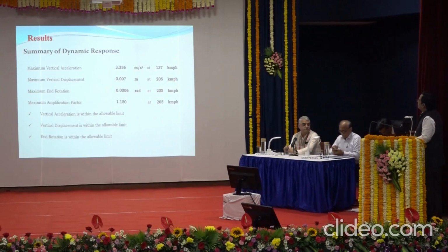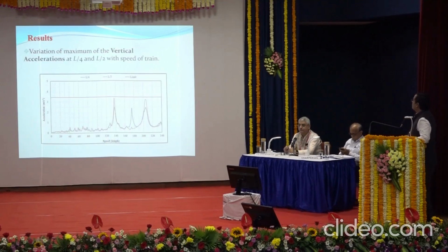So this is the summary. The result was like this. Maximum vertical acceleration was 3.336. Maximum vertical displacement is 0.007. Maximum end rotation is 0.0006. Maximum amplification factor, that is CDA, is 1.150. This was the result. Next, graphically we have shown it like this.